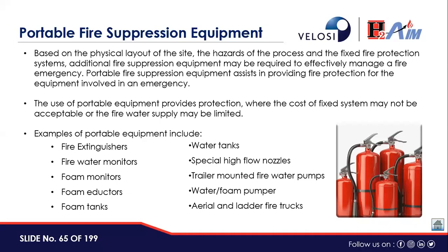Okay, next question. I want to ask about fire protection for LNG production or LNG terminal facility. Is there any special consideration in defining fire protection for LNG? See, LNG is just like a gas, because LNG is normally liquefied natural gas. If, let's say, an LNG tank is leaked, there could be a Joule-Thomson effect, and the balance LNG will convert into ice.